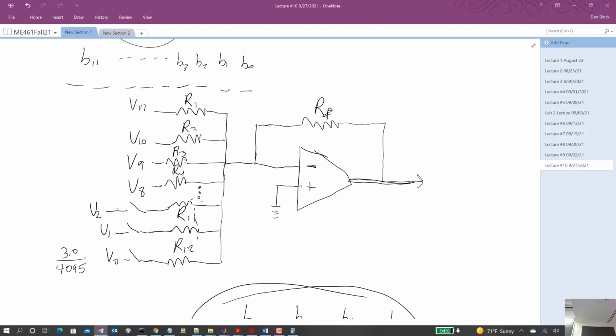The neat thing about the DAC and some of our other sensors or outputs, PWM too, is you just write to the DAC that integer value, and almost instantaneously that voltage is output on that pin. It's not instantaneous. All op amps, if you know much about them, have a slew rate and all this kind of stuff. So there's a little bit of time constant from when you set the DAC to a voltage and it outputs that voltage, but it's very quick.